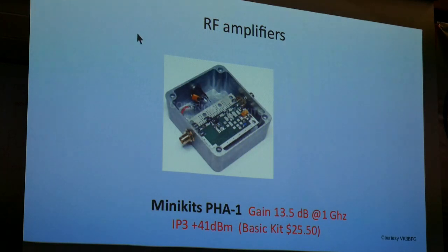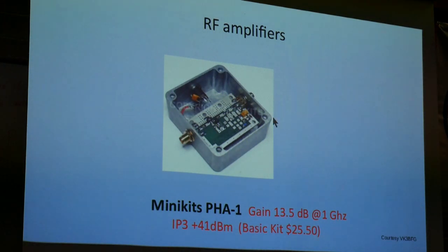So to get that power up, you need something like this, and you can put a few of these in series if you need to get it up a bit more. I've got a couple of these I run in series before I get into a Mitsubishi brick amplifier, or it's a double brick amplifier, in fact, for 23 centimeters. And they're not too expensive.